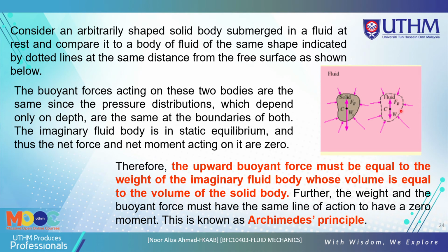and also the fluid. The buoyant forces acting on these two bodies are the same since the pressure distribution, which depends only on depth, is the same at the boundaries of both. So the imaginary fluid body is in static equilibrium, and thus the net force and net moment acting on it are zero. Therefore the upward buoyant force must be equal to the weight of the imaginary fluid body whose volume is equal to the volume of the solid body.